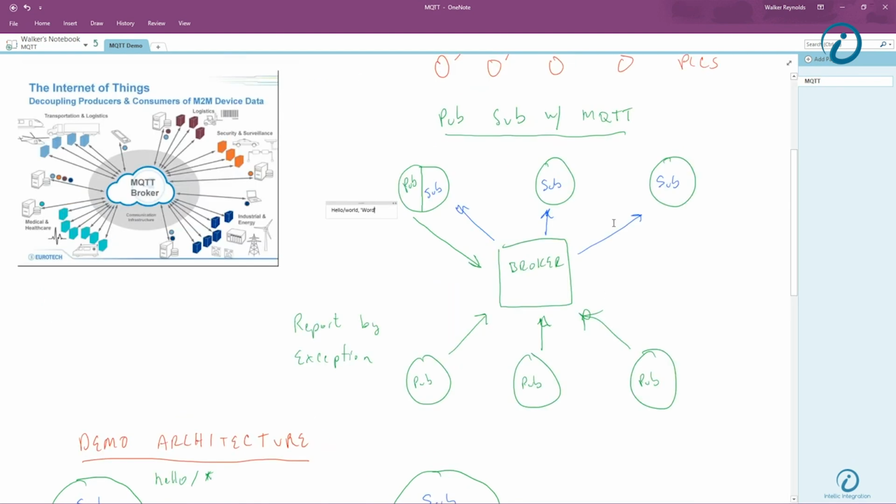So the advantage here is that the header itself, or the packets that get sent over the network, are already inherently smaller with MQTT than they are with other protocols. Much, much smaller. And the fundamental difference is that the agents, the edge devices, are only sending the updated values. They're only publishing the values that change. So let's say that this is an RTU I've got in the field.